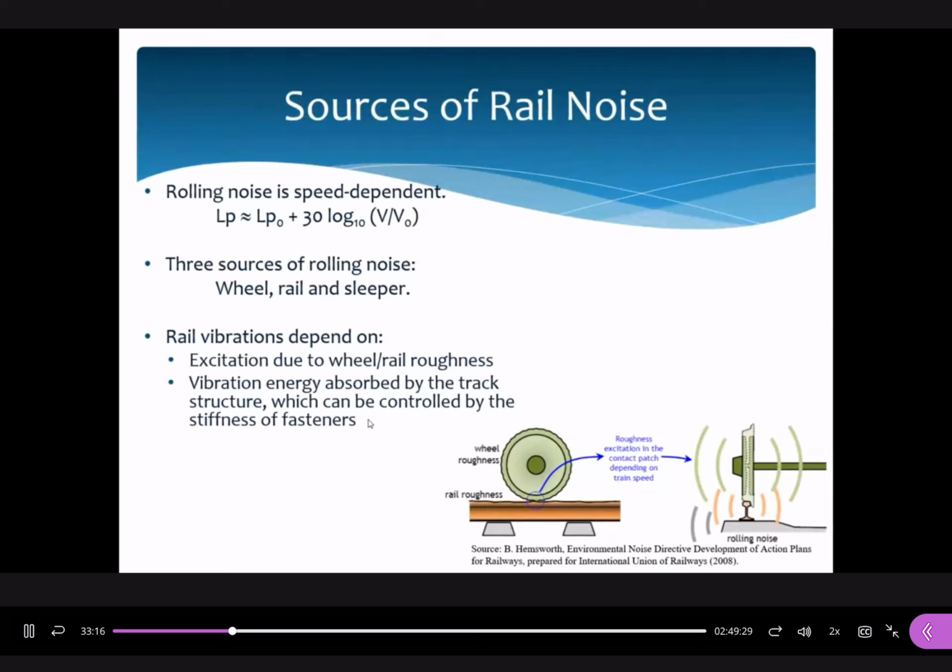For the floating slab track, when you go to Mount Sinai, they proposed the use of this floating slab track. What is the working principle of this one? You may refer to this figure. In this figure, you can see that if we do not impose any vibration isolation system below the dynamic effects, all the force can be transmitted, correct? If we just install some spring systems below the system, we can reduce certain amounts of the vibration energy. If we use a concrete mass in combination with these spring systems, we can further reduce the vibration effects.